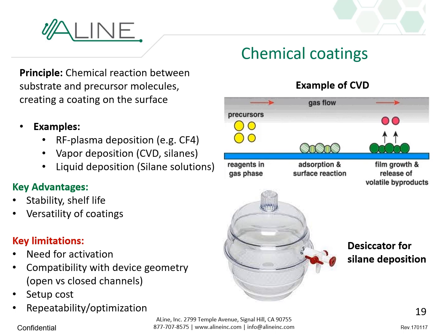Key advantages here is that you do get a relatively good stability or shelf life. Versatility of coatings is also a pretty good thing. However, in its activation, there is always the compatibility with the device geometry to keep in mind. It's typically harder to do deposition inside a closed channel versus an open one, because you have to ensure that the gas flow is consistent throughout a very narrow and potentially tortuous path inside the device.